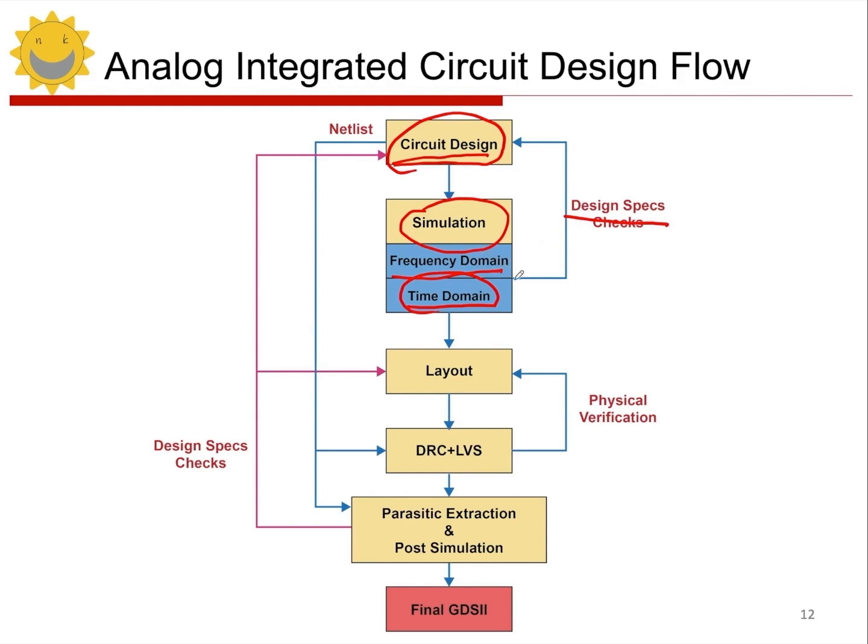In the flowchart, layout directly follows circuit design. In reality, layout involves manually drawing each component layer by layer. Thus, manual work is high, automation low. Also, consider more factors than digital circuits like matching, noise, etc., as poor layout affects circuit characteristics. Now, see how this affects the process.